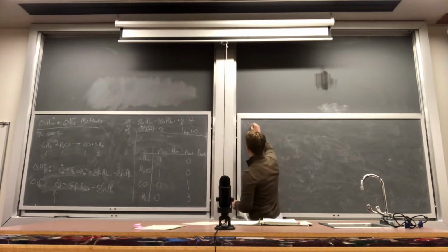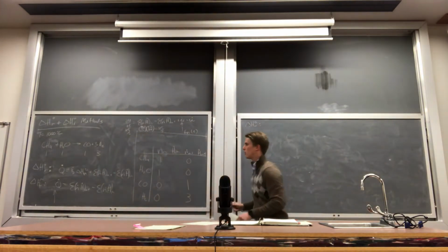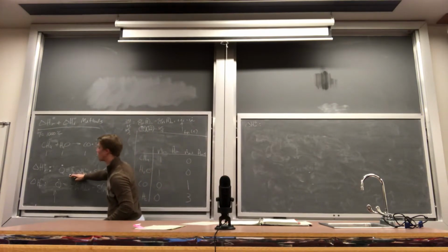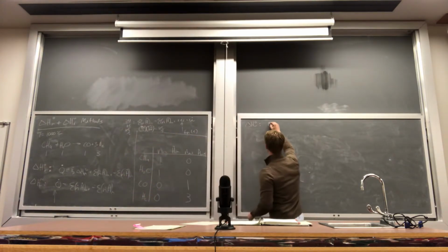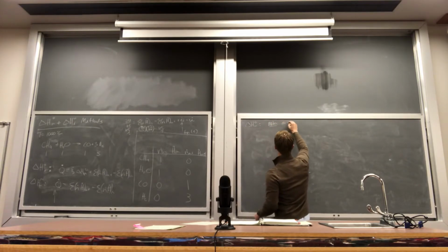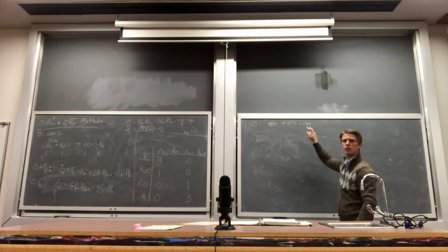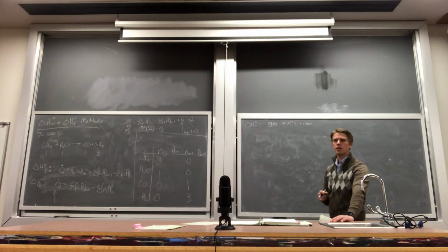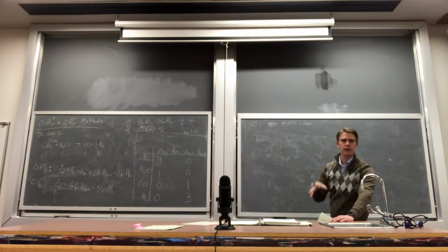All right, for the heat of reaction method, we have a different energy balance where we have all of these individual terms here corresponding to the extent of the reaction at the standard state. So these terms here will be different based on the reference. Here the reference, of course, is the molecular state at 25 degrees C and 1 bar. For the most part, we don't have to worry about the 1 bar because we're not super diligent on calculating enthalpy changes of material as a function of pressure, but we say 1 bar here just to remind us that this is at sort of room temperature and pressure. Is it going to be a liquid? Is it going to be a gas? Whatever the case is going to be.